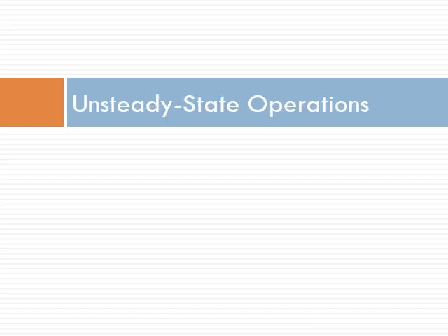In this lecture, we're going to talk about unsteady state operations. Just to remind you, we said we have a few cases, actually 4 cases, where X is not our preferred variable to be used in a design equation. Therefore, we're going to use the design equation written in terms of molar flow rate, or concentration, or number of moles. And one of the 4 cases is unsteady state operations of non-batch or continuous flow reactors.